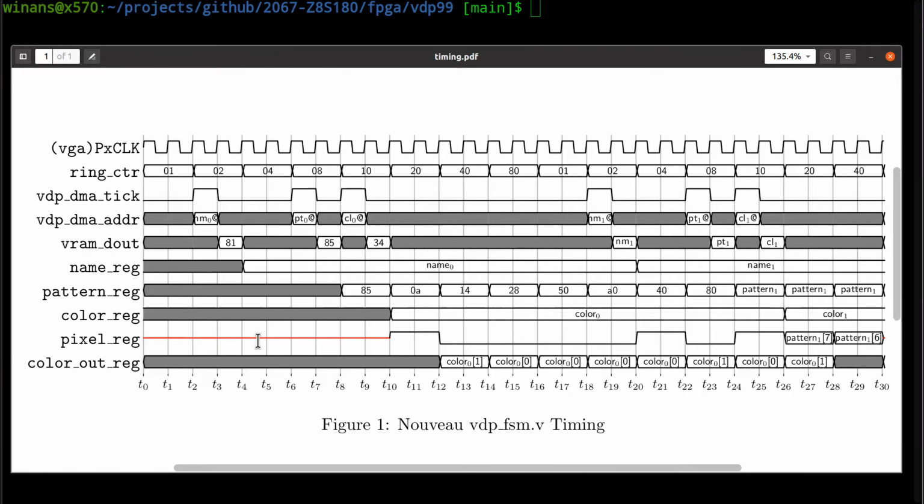So what happens is it's all driven from the VGA sync module I talked about on my channel before. That module generates things like the VGA column number, the VGA row number, and signals that say this is a good time to be showing the border color, this is the period of time on the horizontal rows where we've got an active display region, and then another border on the right, then the front porch and the sync, and all that comes from the VGA sync module.